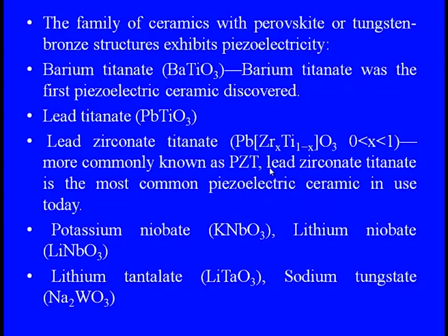The family of ceramics with the perovskite or the tungsten bronze structure can also exhibit piezoelectricity. We can talk about barium titanate, which is one of the basic piezoelectric ceramics, or lead zirconate titanate, PZT, which I showed previously, which has excellent features, and that's why we use it commercially. Or even potassium niobate, KNbO3, lithium niobate, and sodium tungstate can be used, all clearly showing piezoelectric features.